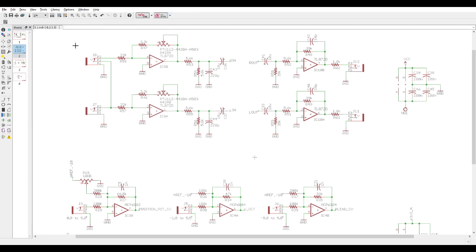And what Emily Gillett has done here is also publish the interface circuitry. So this is the input side. It's taking Eurorack levels and buffering it with dual potentiometers into levels that are suitable for that codec device, and then taking the outputs from it and again buffering and amplifying them up to Eurorack levels.